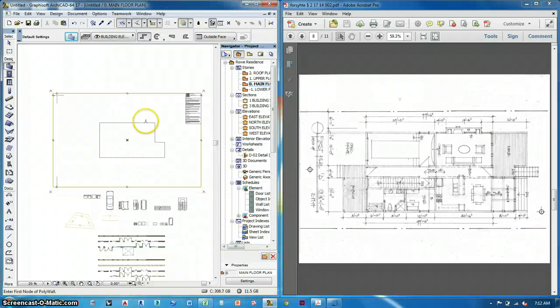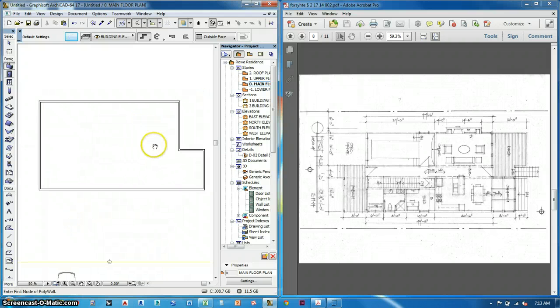So now what I can do is, if I just hover my mouse over the edge of this till I get that little trident, or Mercedes-Benz without the circle, I don't know what you want to call that, wishbone, peace sign, I don't know. You go over and you hold down the space bar, you'll get this magic wand. And you can see the magic wand icon also change when you get to an edge. And once that icon changes like that, I can click, and there's my wall. It goes right around the whole slab.